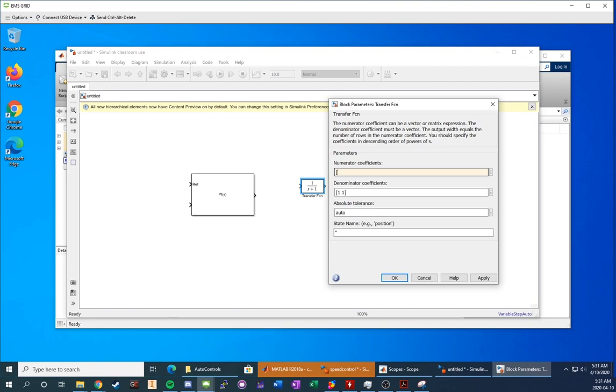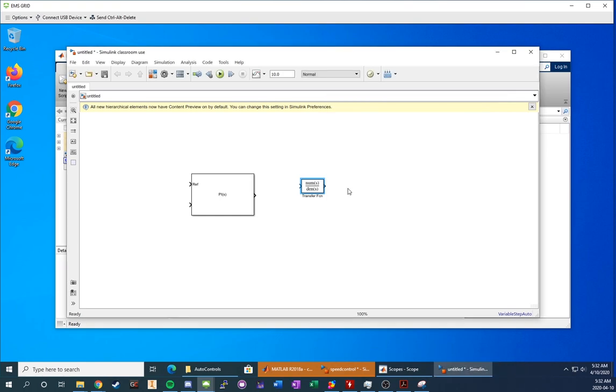So in our case, we're going to be doing the k value divided by tau, and that's just going to be a signal gain, first order. And then on the bottom, for the S term, we're just going to be having a 1, and then we have 1 over tau. So those will be your values. Making that a little bit bigger so you can see what the transfer function is there.